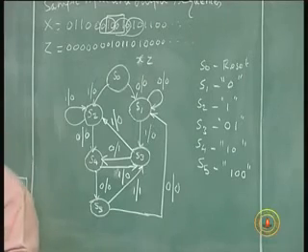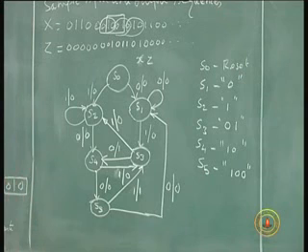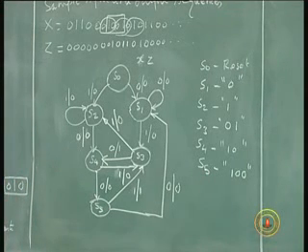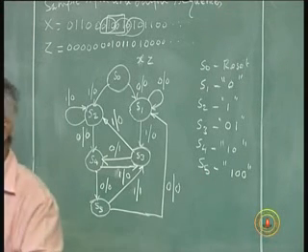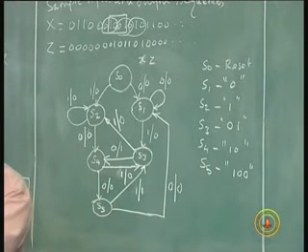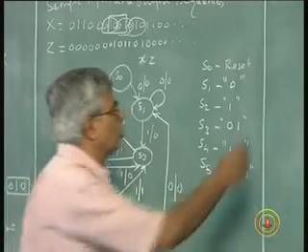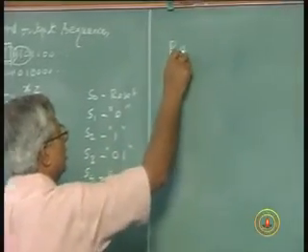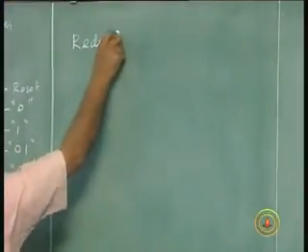This is called assignment. Once you have a state graph with state symbols rather than binary values, converting the states from symbols and letters into binary variables is called a state assignment. So one is reduction of states, reduction of the state graph.